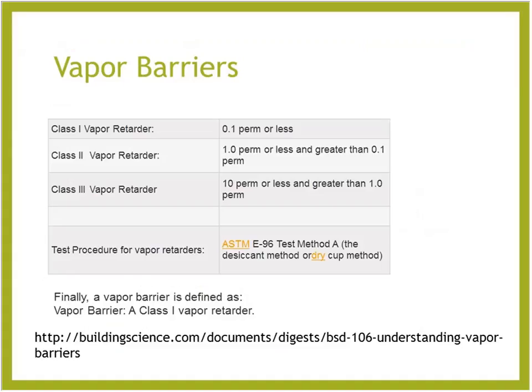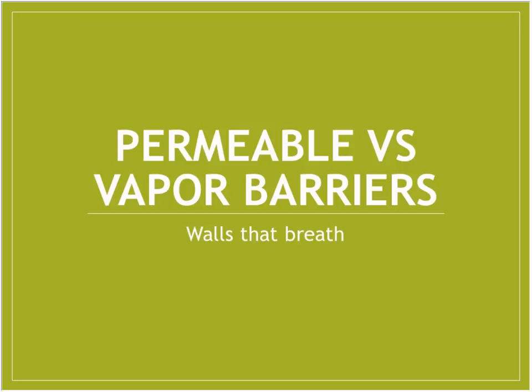Lots of great resources there, and education and studies on wall assemblies that keep water out. Some other thoughts that are going out there is this concept of permeable versus vapor barriers, or versus impermeable barriers. And the argument from others, and we have a session that's coming up on this called Walls That Breathe, is the concept that walls breathe. So not walls that breathe air. We don't want the walls to breathe air, remember, from the last session, the health session, but we potentially may want our walls to breathe moisture.